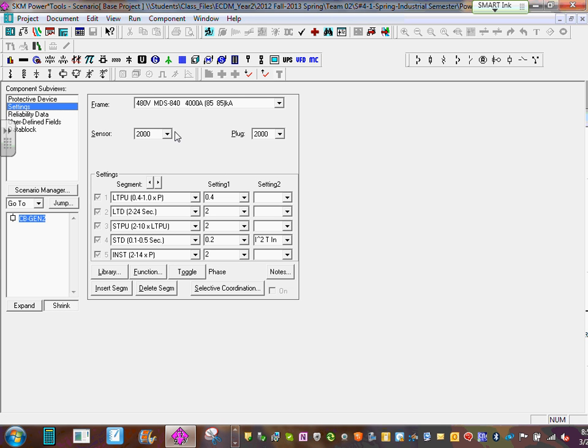Now I said I need a 2500. Here's what your default is. Go 2500 amp, go 2500 amp, and Adam, go make this one 1. So I have a 2500 amp circuit breaker for this generator, based on the size that we have.